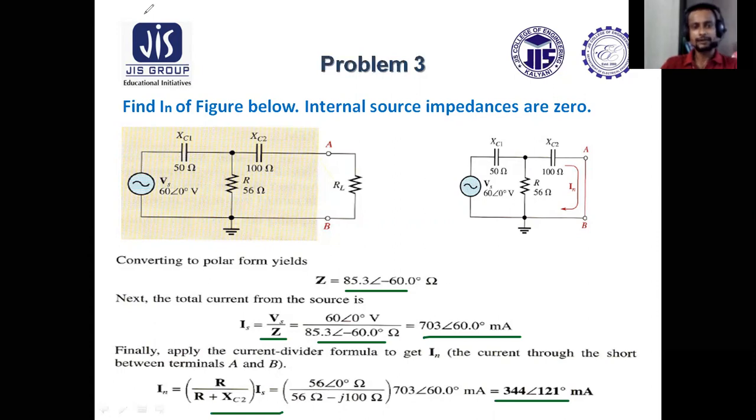If a circuit has a single source but a lot of complexity, then Thevenin's theorem will be suitable. If the source is a voltage source but a current source is given in the network, then Norton's theorem will be more suitable compared to Thevenin's theorem. So depending on the type of circuit, you may apply superposition, Norton, or Thevenin's theorem.